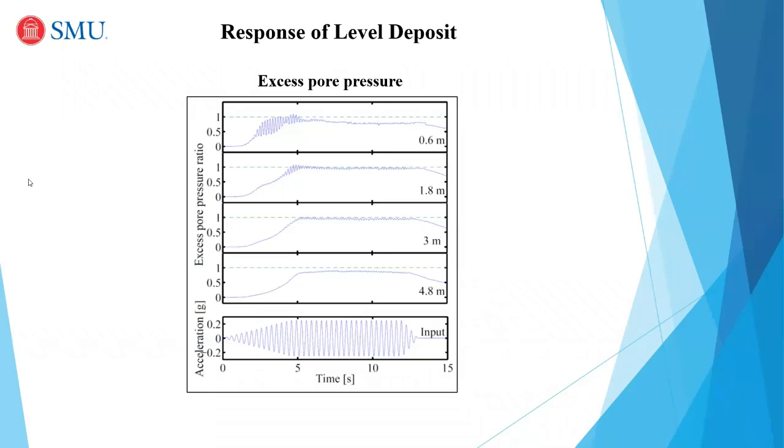So by squeezing the void space, pore pressure starts building up, pushing back the grains. Now, if the pore pressure generation wins, meaning it's capable of pushing back the grains enough, then you will end up having these grains separated, and you will have grains that are essentially floating. So you can imagine now your soil that was supporting a foundation turning into basically a soup.